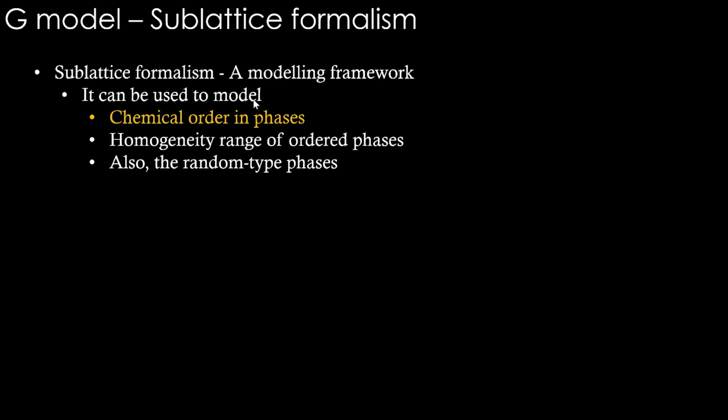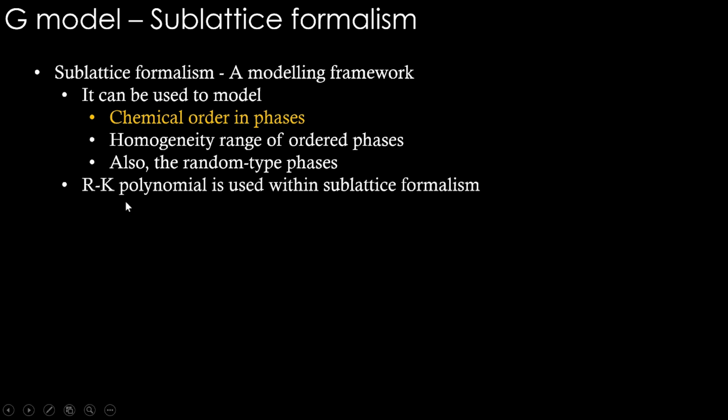What we have seen initially for solutions is without any sublattices. We just said this is a solution phase, this is a chemistry, this is a Gibbs energy. We just used the RK power series to describe that. Here we are saying sublattices can be put even for solutions. So we are going to use this sublattice formalism everywhere, even for solutions. So the RK power series is used within this sublattice formalism to model the phases.